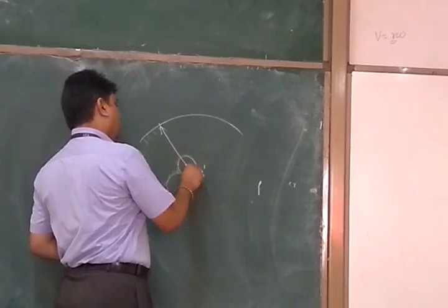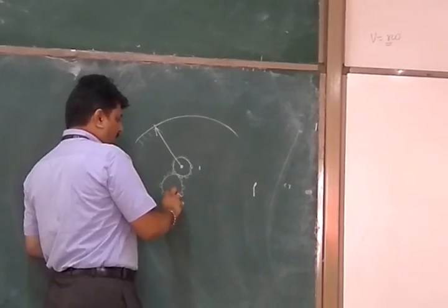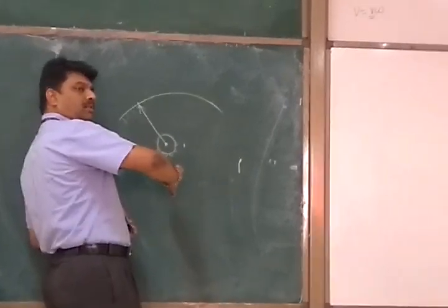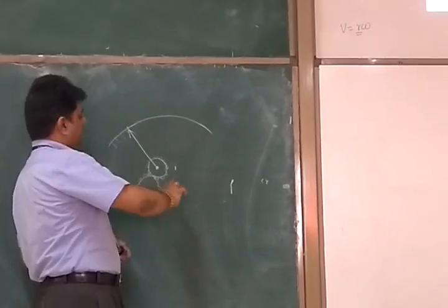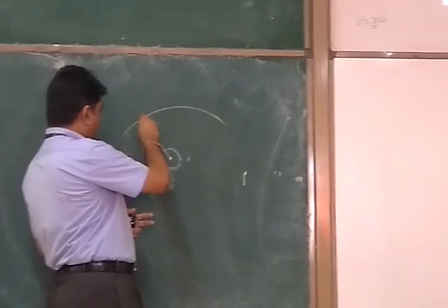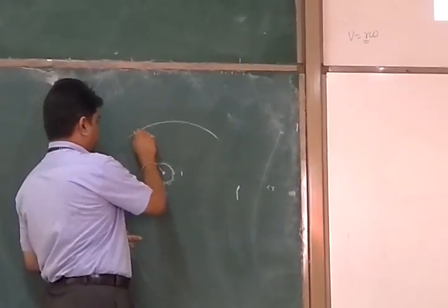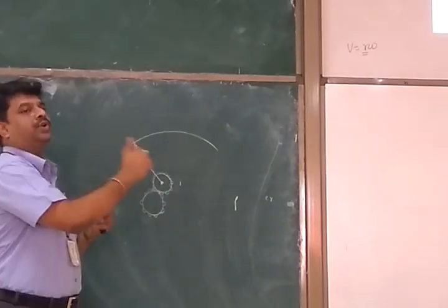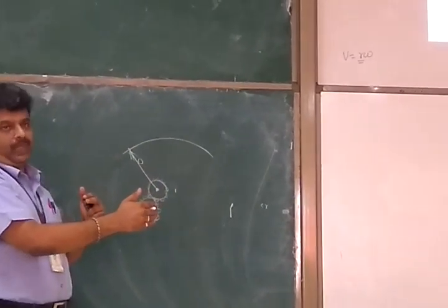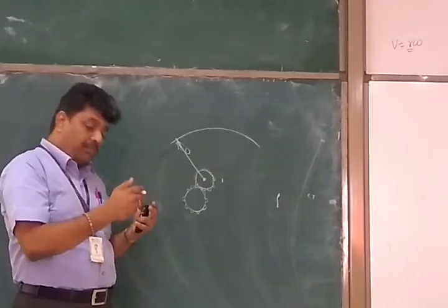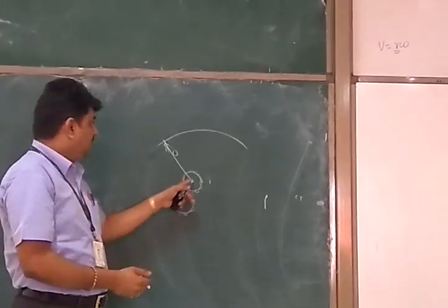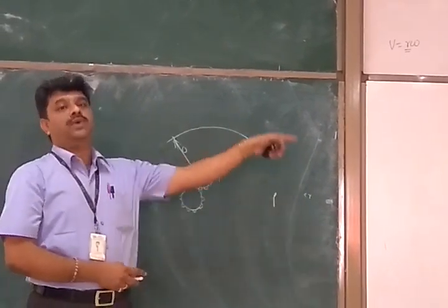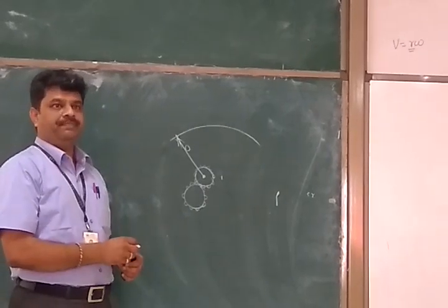Okay. So now, while rotating, for some movement in the reversal direction, in the last measurement I took, the needle has come back to 0, and now it is in the 0 position. Let's say this is the 0 position. Now it has to start rotating in the reverse direction. But because of backlash, for a certain amount of movement of this gear, the pinion won't rotate. But I want it to always rotate, however small the motion is.